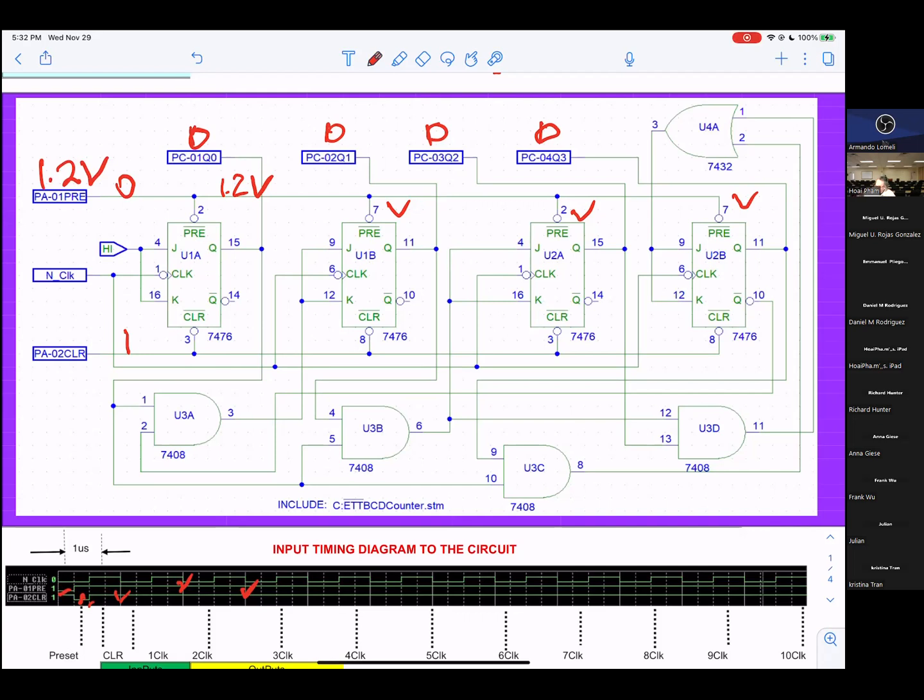Then what do you think you can do? Replace the box that we're testing, the unit box. Yeah. That means you can try to reset the control box, right? Press reset. After you reset, then at least in the control box, 2 LED have to be blinking. If they are not, that means the computer is not talking to the box.